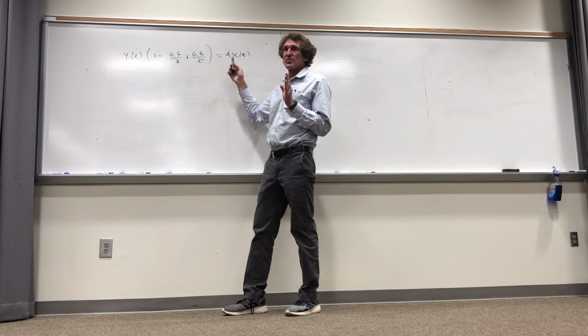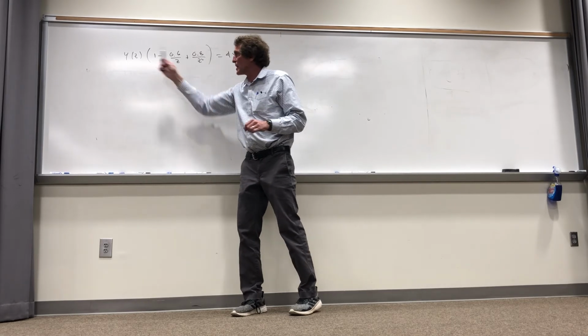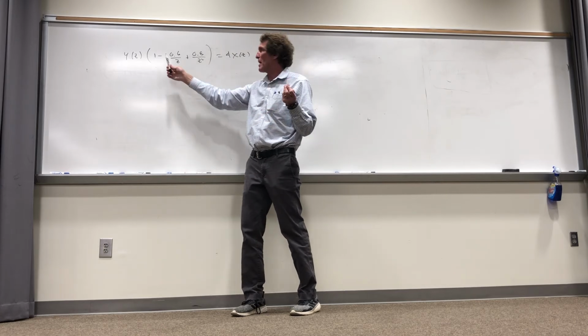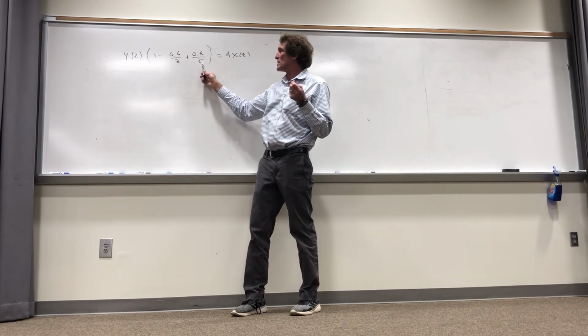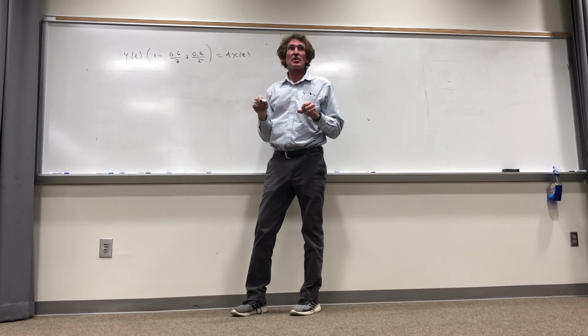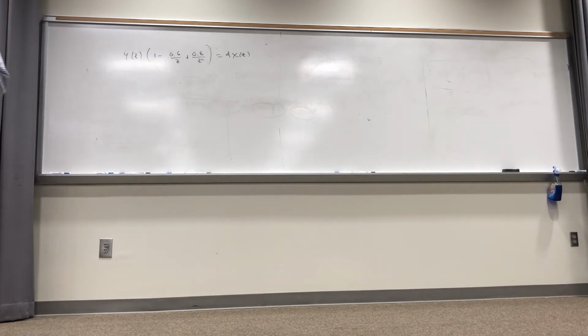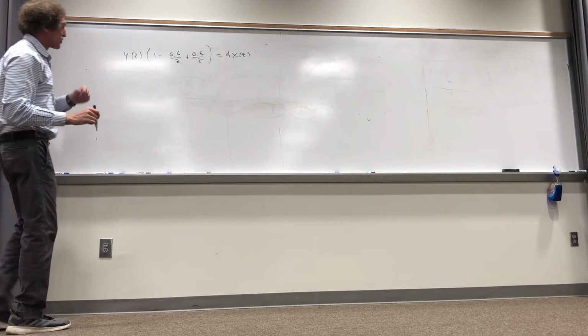Now I didn't want to start with the transfer function. I want to start here because at this point, you get y of z where the highest power is 1, and then z to the minus 1, z to the minus 2. We can build a circuit with delay operators that will achieve this input-output relationship.